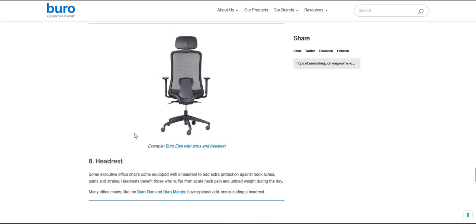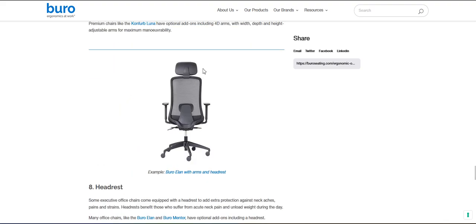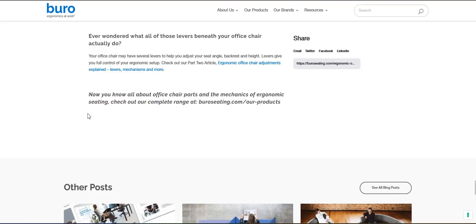The arms, if we're going to have them, mostly this one is going to be, just let me check the chair I'm sitting in. Yes, it's plastic, yeah, plastic and plastic, yep. So the handles can be plastic, unless they're going to be able to go up and down, and thus we're going to need some sliding mechanism, which requires metal. The headset, if we have them, like this one, is going to be once again plastic injection molding, and we can use some foam and fabric on the top of it.